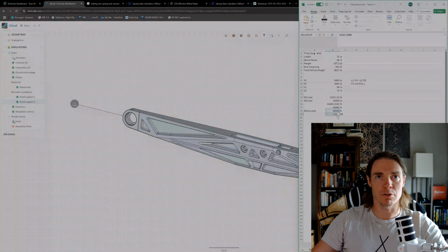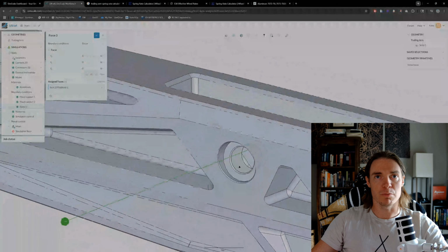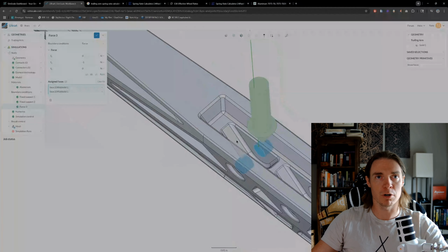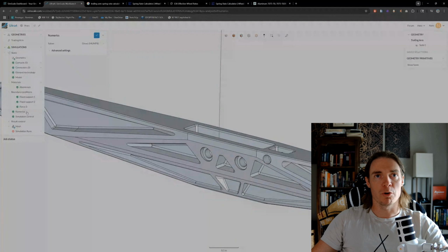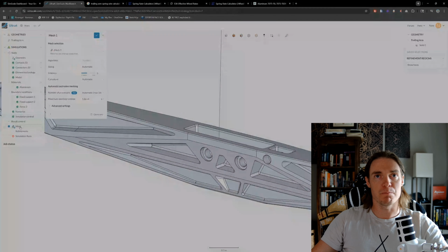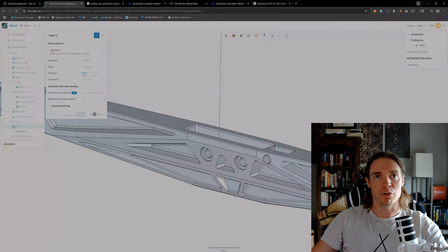imparted. I'm just looking at the forces imparted on this part, and in an idealized case, the only forces on this part would be experienced in the 2 fixed supports where it interfaces with the rest of the assembly, and then the shock load right in the center. So I need to put this shock load at the corner weight times 5, which ended up being 90 kilonewtons. That 90 kilonewtons is a lot, but this is going to be a really strong part.